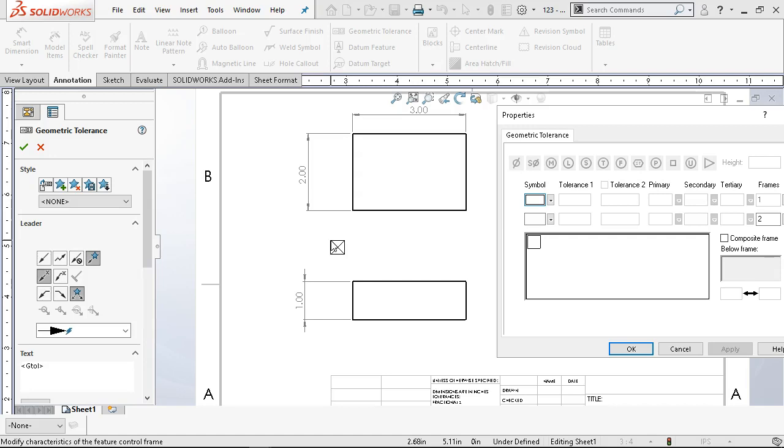Whatever shop you send out to quote, whatever shop you have within your company, they're going to look at that and say, this is the equipment that I have that will hold those tolerances. This is how we're going to make it. You can have input on that, but the drawing does not drive. The machinist, the manufacturing group, they drive. So we're setting controls that say we want a desired outcome, but they determine how to get to that end.